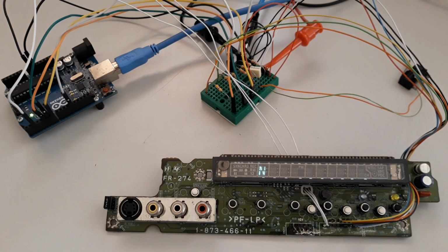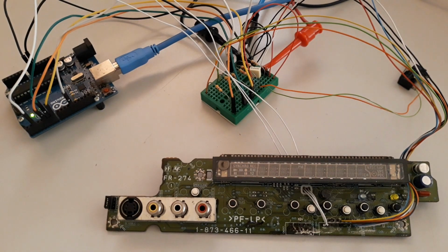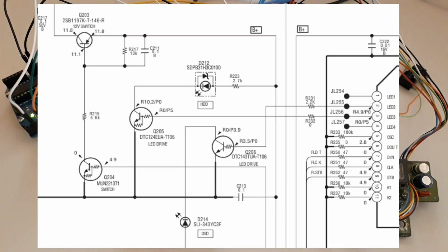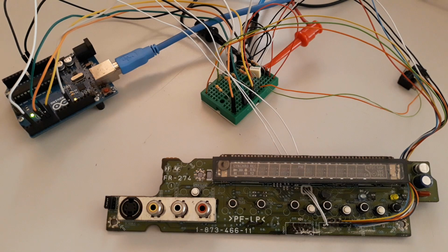Once again, I would like to highlight a small detail, which is the presence of 2 transistors as a driver for the LED. The 2 NPN transistors, reference Q205 and Q206, being NPN, will leave the LED on when we apply the high value to the port connected to the base, remaining in the reverse operation.